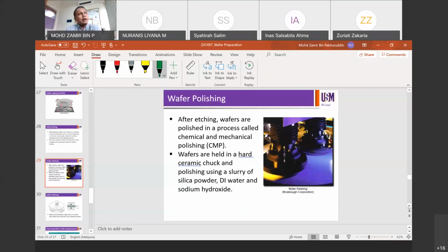If you look at, for example, Silterra, it has one department called CMP. The way it goes in a wafer fab, at least for Silterra, I don't know how others are operating, every process is categorized as one department. So that means etch is one department, thin film deposition is one department, CMP is one department, implantation is one, diffusion is one, oxidation, and so on and so forth. In every single department, we will have process engineers, equipment engineers, and some process technicians and equipment technicians as well.